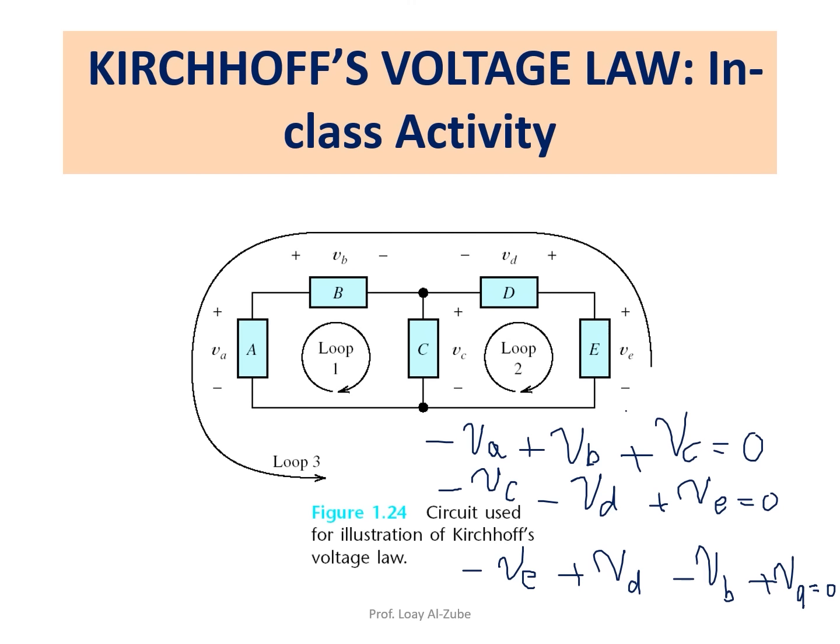And that's one of the things in electronics and instrumentation. Devices sometimes don't work, not because there's something wrong with the power, or something wrong in building the circuit itself, but the instrument will stop working because they don't satisfy Kirchhoff's voltage law. Does that make sense? And I'm going to show you an example. Any questions about the loops? Any circuit, you need to build all the loops. You need to find out all the equations for the loops.